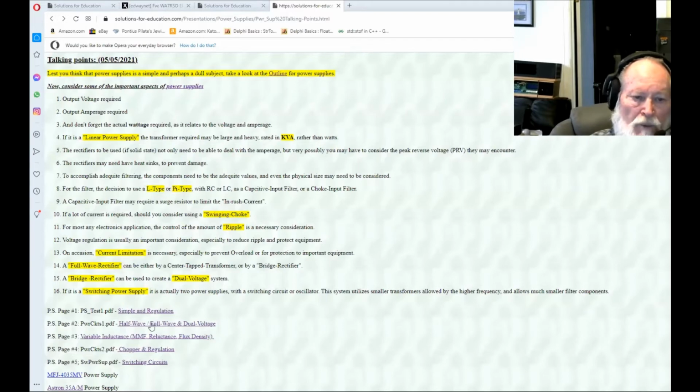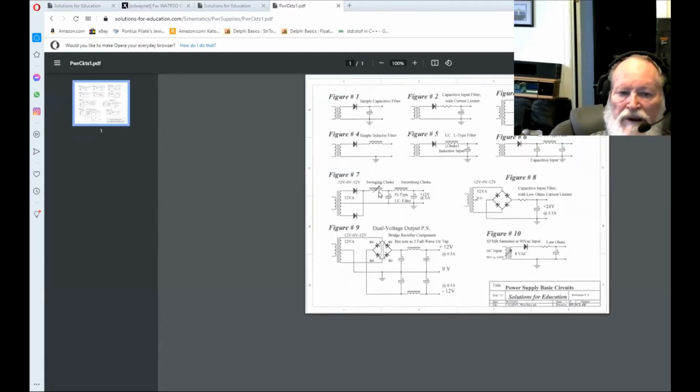Going back here to where we were a minute ago, this guy here is what we're talking about. As you have less current, you may have 25 henries. But as you finally wind up with more and more current going through, and remember, on the very slope of the current, this guy here can diminish and become only 5 henries. However, this circuit over here, whatever henries you got here, if that's 15 henries, it's going to be 15 henries all the way. Will it ever saturate?